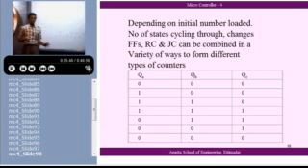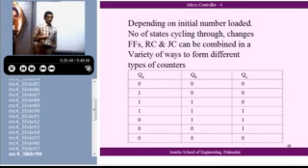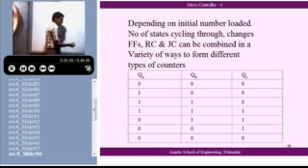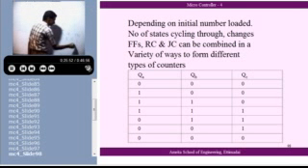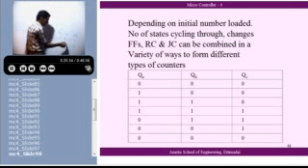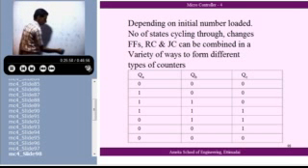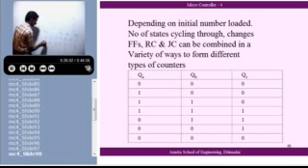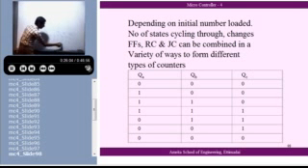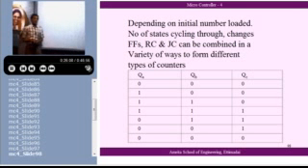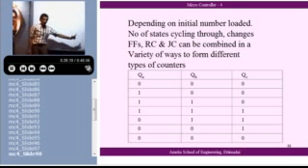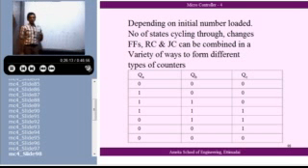I connect them as a ring counter and shift in this direction. When you give one clock pulse, that 1 will get shifted here. Next clock pulse, it will get shifted here. Next clock pulse, it will get shifted here again. Okay? I have made a new counter.